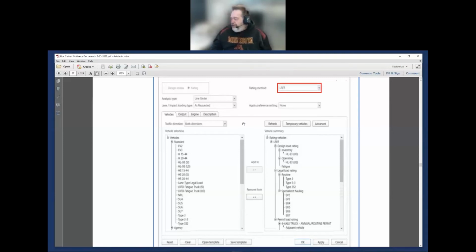Later on, a couple of our refinements will ask you to go into the Advanced tab here, and inside the Advanced tab you can apply a scale factor to some of these loads for the amount of load that gets bypassed. The access to those scale factors is through this Advanced tab here.